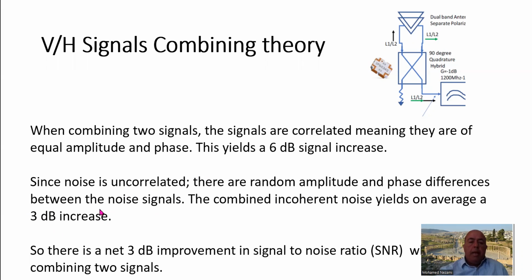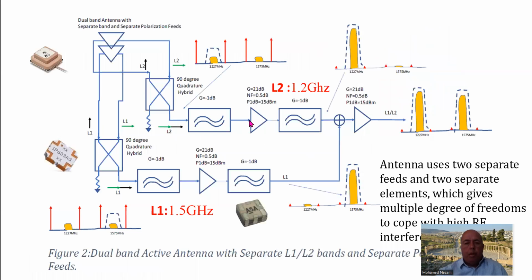So the overall increase in the signal level is 3 dB when you do this scheme, where you combine the polarizations, a polarization combiner you might say. That's the principle of why we use the quadrature. You could leave out the quadrature and pick up the signal from one single polarization, but then you lose 3 dB from the available signal.